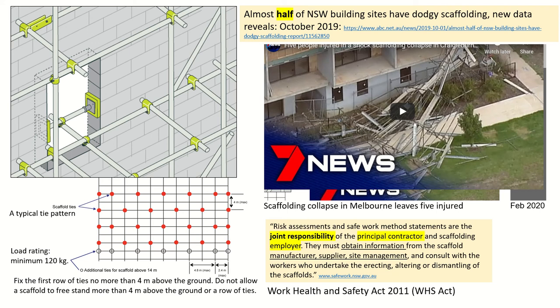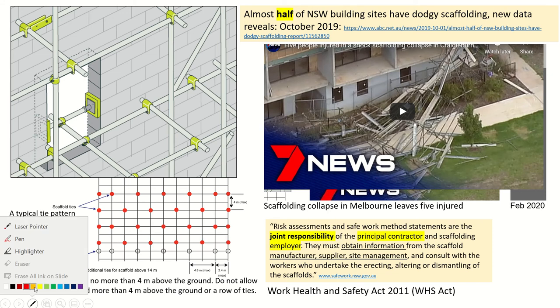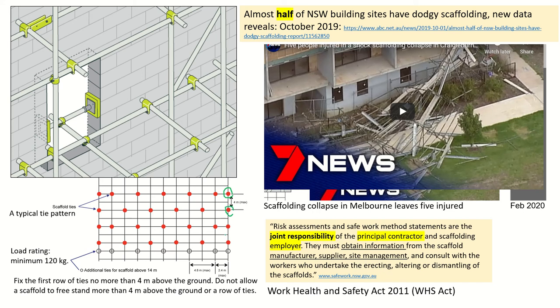So this is one of the key items to be considered when you do scaffolding. For example, the distance between joints shouldn't be more than 4 meters. Also, from the ground level to the top, the first row of ties should again be less than 4 meters, and the minimum load that should be considered is 120 kilograms.